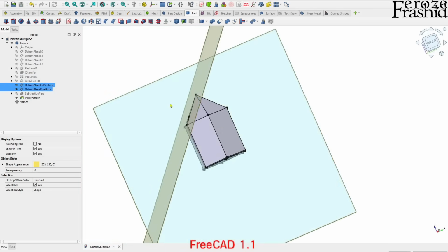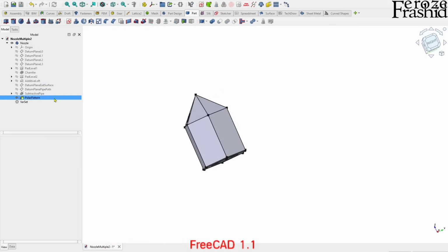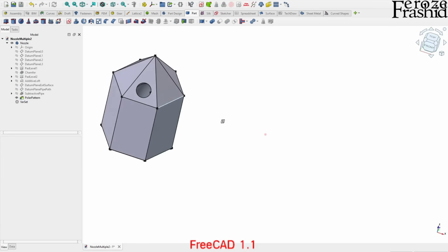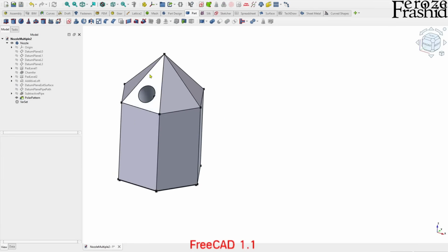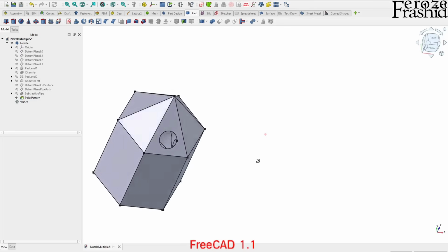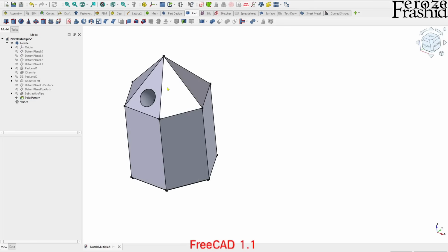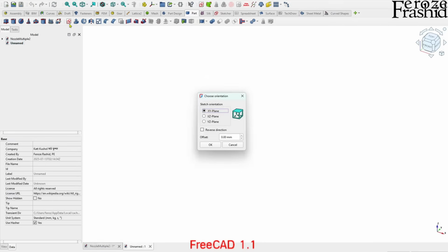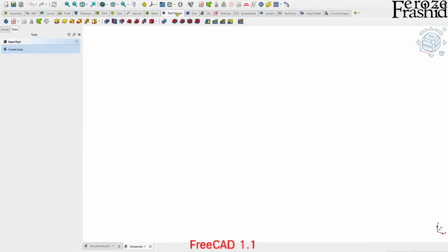Okay. A lot of datum planes, and the goal is to have this nozzle, and I think I can build this nozzle pretty simply without the datum planes. And tell you what, I'll just build this thing from the ground up so we can rule out any other interference and any other unnecessary features on this model. So let's open up a new file. Here I will draw, let's do that in Part Design.